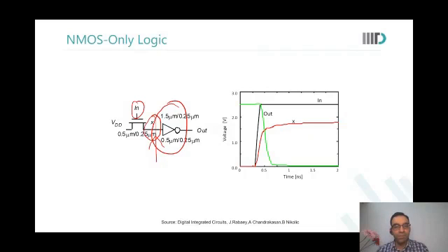Sir, what do you mean by current exactly, sir? Output current, sir? What do you mean by current of an inverter? Sir, the current to the load which it supplies. Do you mean only that when you talk of current? Current from the VDD, sir. Yeah. So what happens to the current from VDD over here? That is what my question is. So subthreshold starts from PMOS and something more maybe. Now the PMOS is not fully off. Yes. So the PMOS current or the subthreshold current or the static current that will flow will not be zero.